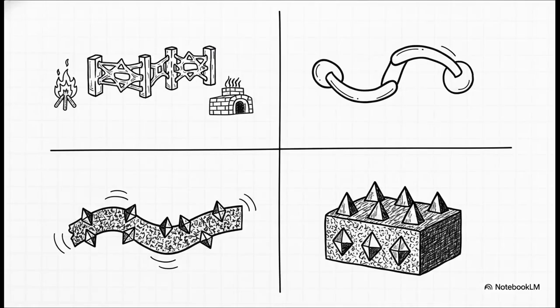The real secret sauce of a wheel's performance often lies in that middle element, the bond. The specific strength of the bond determines the wheel's grade and toughness. You've got vitrified bonds, which are essentially glass and ceramics fired in a kiln at a blistering 1250 degrees Celsius. They are incredibly rigid. Then you have resinoid bonds, made of thermosetting plastics for a bit more flex.